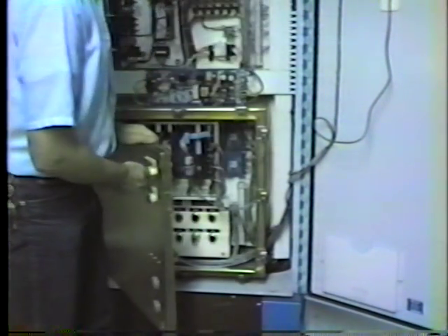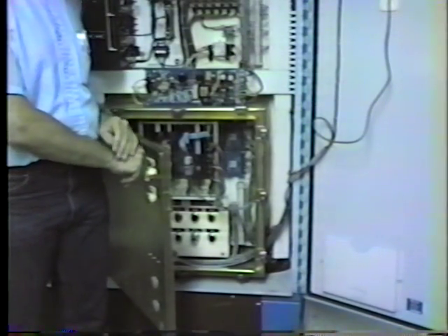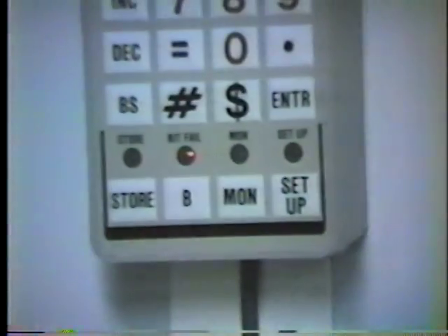And we fixed the problem, but even after fixing the problem, when we turn the computer back on, power on, we're still going to get the failure. We've still got the failure up there. We have to acknowledge to the computer that we have fixed the problem. That will aid in finding intermittence and things of that sort.